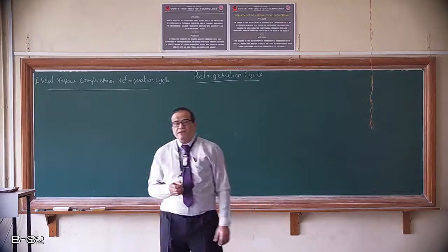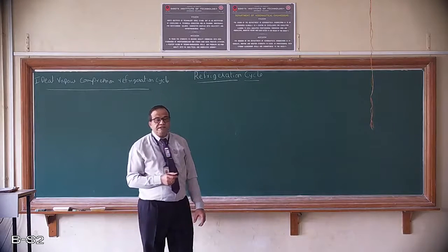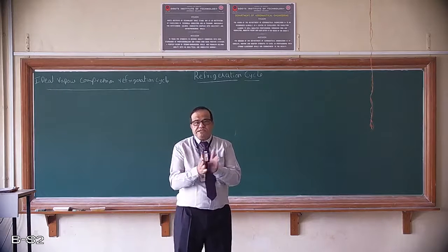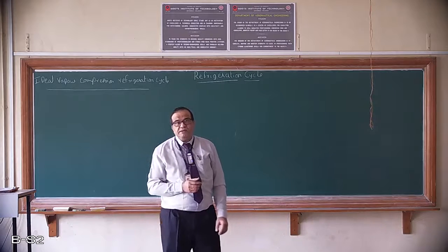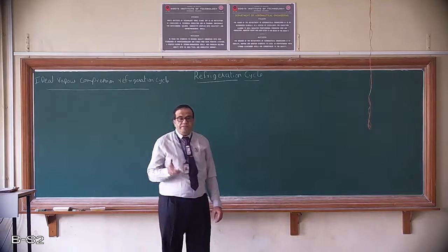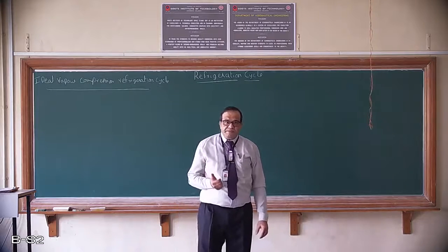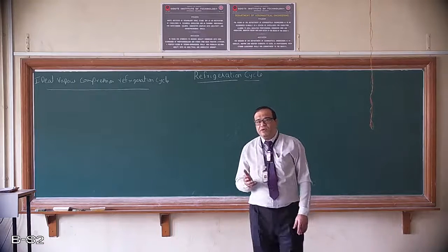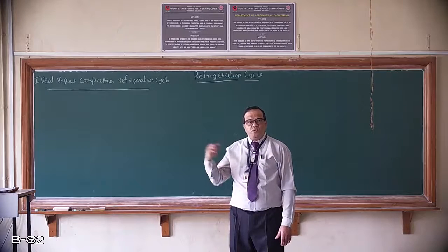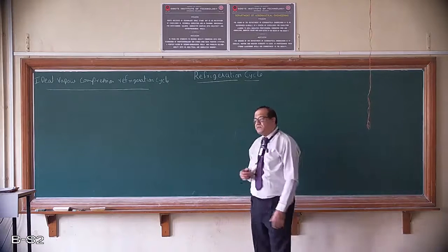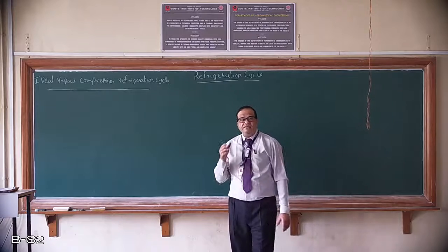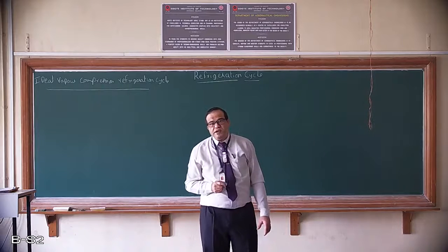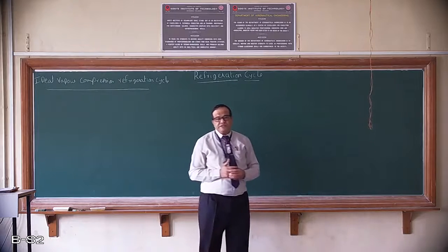We need to have an expansion valve. What is an expansion valve? Basically a device where suddenly a medium is expanded. What exactly happens when we do that? We have a drop in pressure and a drop in temperature, and that concept is used basically to cool the medium. In a refrigerator, you need to cool the medium kept inside, so for that reason we have an expansion valve. Sometimes capillary tubes are used, especially for a small refrigerator. For a larger refrigerator we use expansion valves.